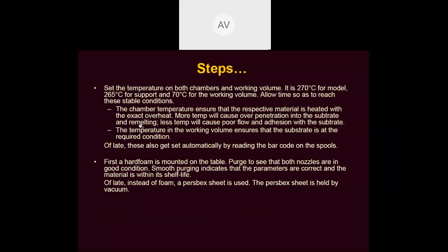Then set the temperature for both chambers and the working volume. It is 270 degrees for the model, 265 degrees for support, and 70 degrees for the working volume.